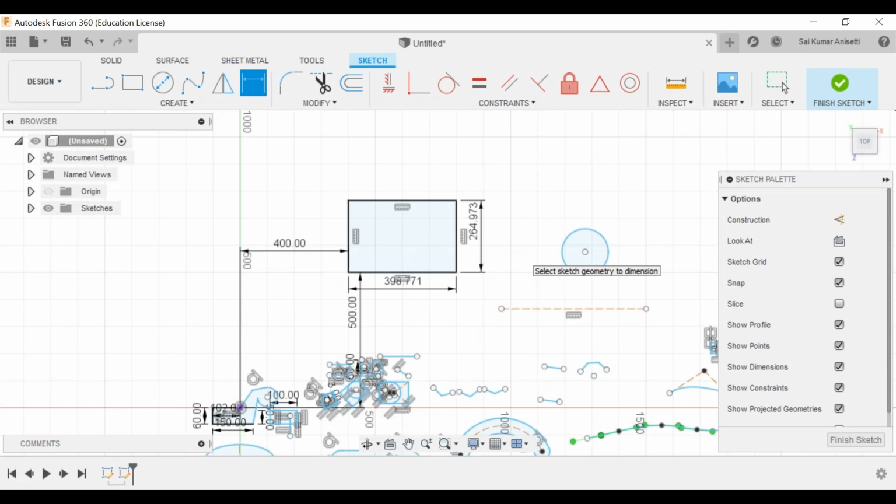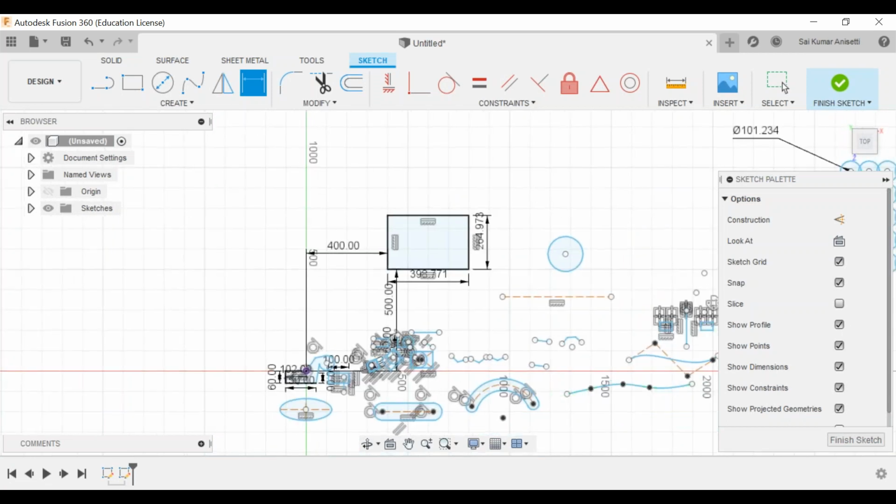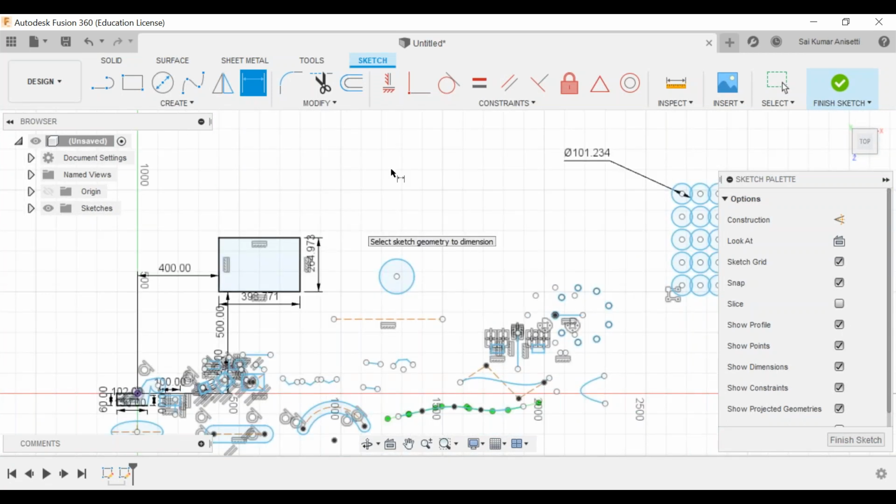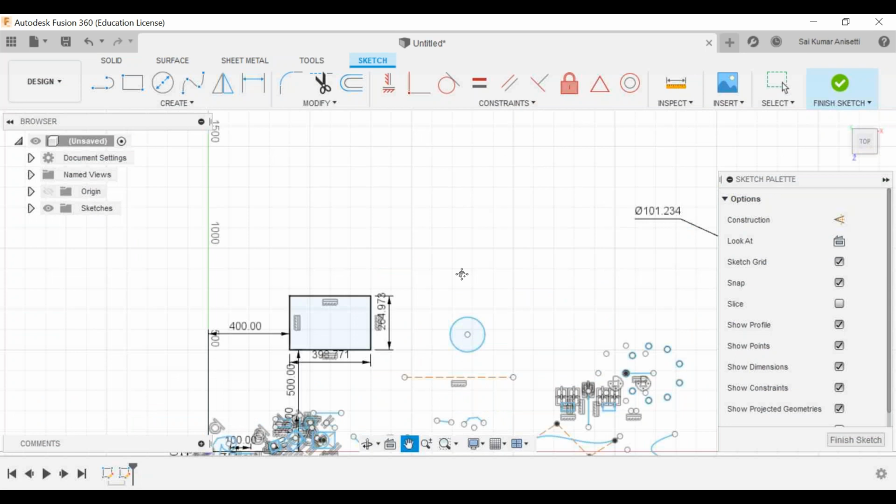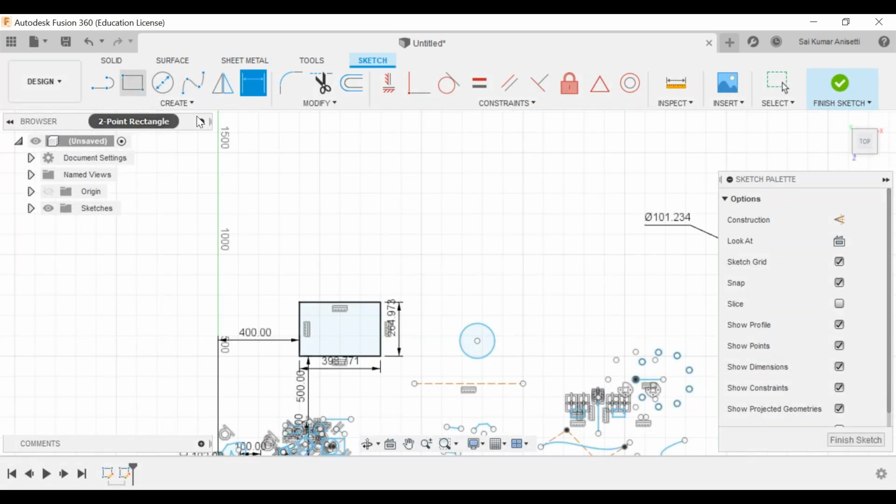Now you have to practice your complicated sketches. In your complicated sketches, try to give your angles. First, try to close this profile, give your dimensions between these two profiles. Finally, take a point in that profile and give horizontal distance and vertical distance, so that the entire profile gets fixed. Let me show another example also, as an irregular dimension.